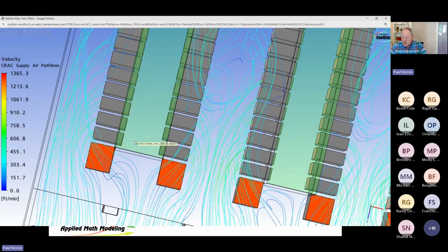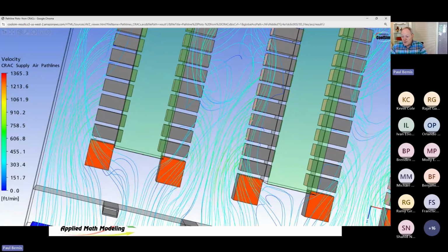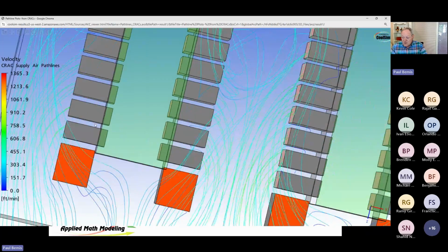And this pressure in here, remember you've got two high-speed airflows coming at each other, and they meet in the middle and go to zero and up and out, or near zero. So it's not unusual that your pressure in your hot aisle is a little higher in certain areas than the pressure in the cold aisle, even though you're supplying more air than you need. It becomes localized. And that's the power of CFD, is understanding that local behavior.